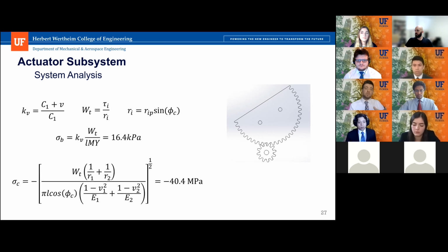Essentially, since this would be rotating over the entire day, a portion of a rotation over the day, and then reset at night, you can assume it to be 2 cycles a day. And so there's going to be the wear on it, which is what the pitting and contact stress relates to, would be very low. And both of these numbers are extremely low compared to their respective material properties.